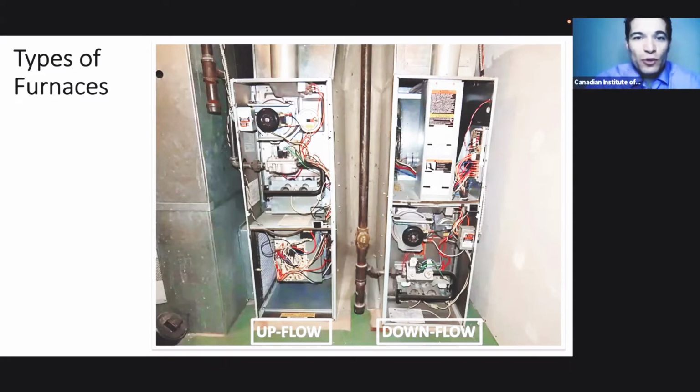Looking for any sort of flame rollout, which we'll talk about in a little bit, any corrosion, any watermarks. And of course, your audio and visual clues as well. If you hear any squeaking or rattling, that should be a sign that some servicing is required. And of course, if you smell anything burning. We're going to be talking about gas detection in a little bit, but those are some additional tools that you want to bring to the job site to make sure that you're doing a decent inspection.